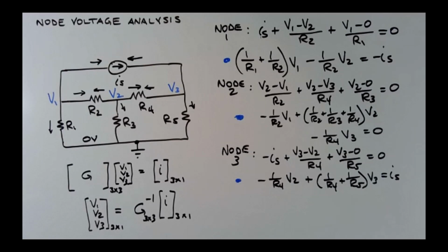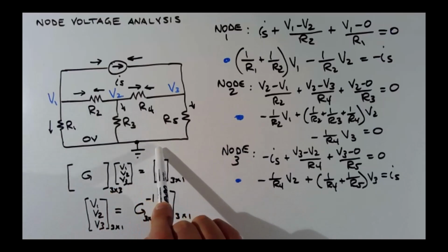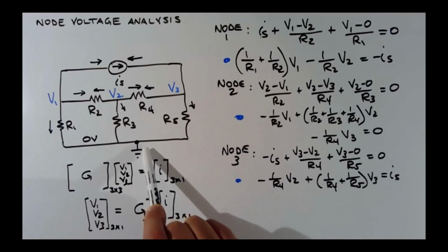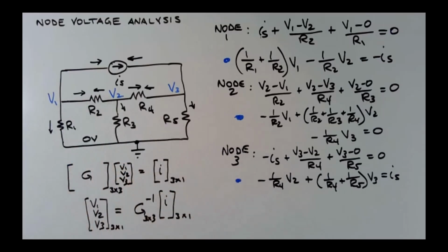Okay. So this is node voltage analysis. When you're asked to do node voltage analysis, look at the circuit. There's probably a ground defined for you. Keep that, use that, and write a KCL equation using this technique at every non-reference node, and then solve. Questions on that?